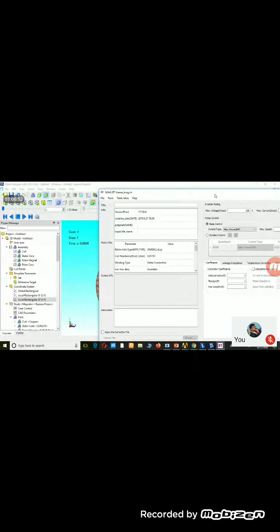So again give the option as more. Now giving the efficiency map. There are two maps available, one is the speed torque characteristics and the other is the efficiency map. So coming to the analysis point of view, in case of mechanical, when we go with the thermal it will be easy. The JMAG RT Viewer will run for some time. In the meantime, we will see the thermal characteristics. In case of JMAG also, we can do the thermal analysis.